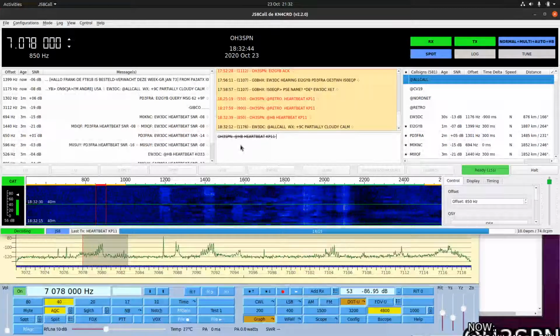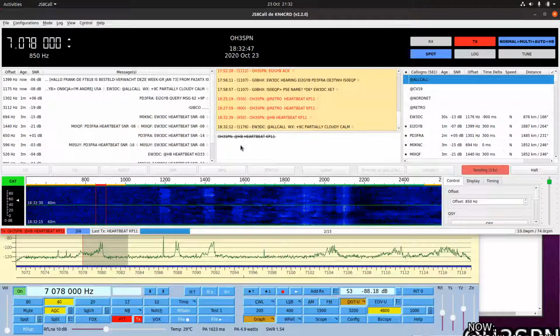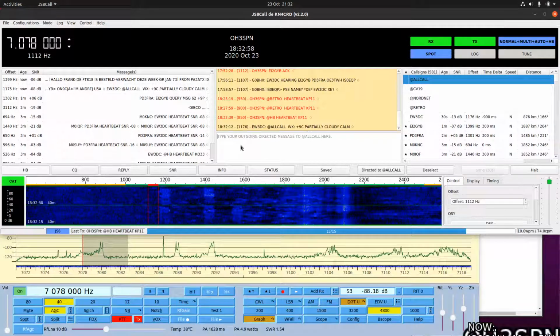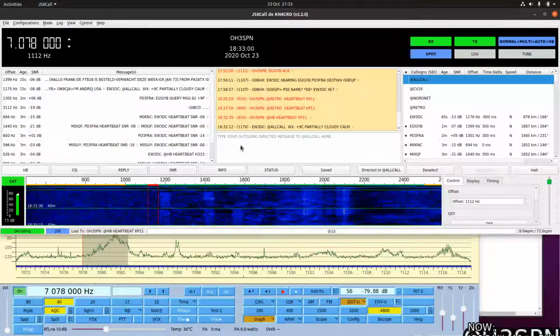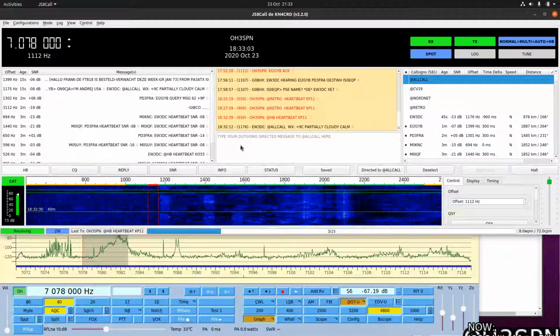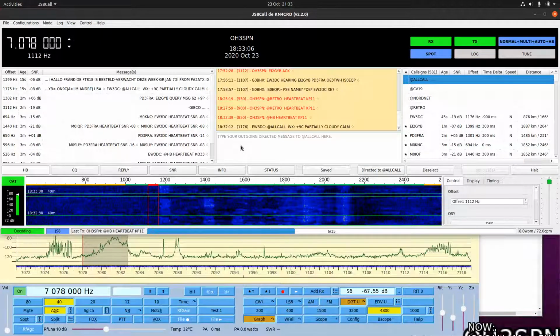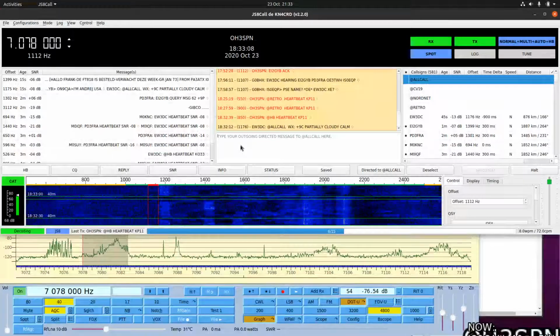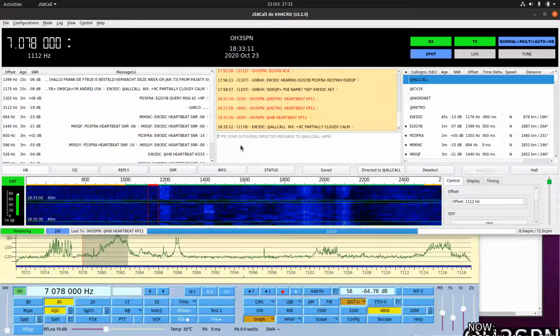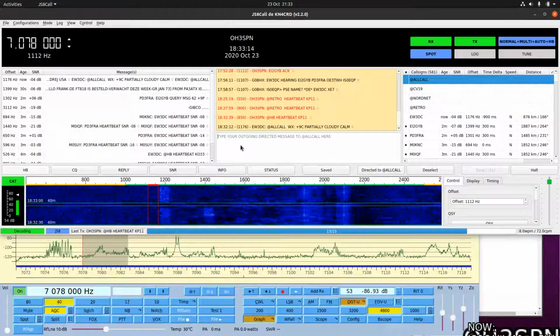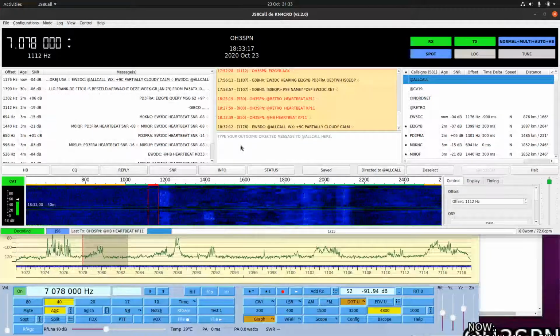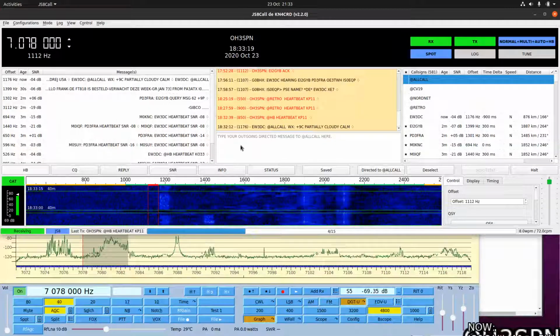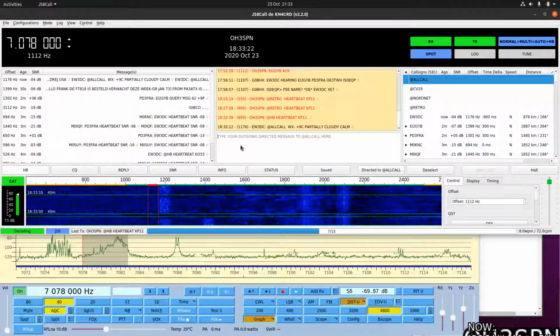I can even switch to FT8 if needed. And by the way, my antenna is not great on 40. The SWR is about 2.5 to 1. I'm running a small LDG ATU just on 40 meters on the Hermes. The Hermes is perfectly fine delivering power into a poor load, but I like to just keep things sane, and not strain the finals, the PA, any more than I have to in the Hermes.